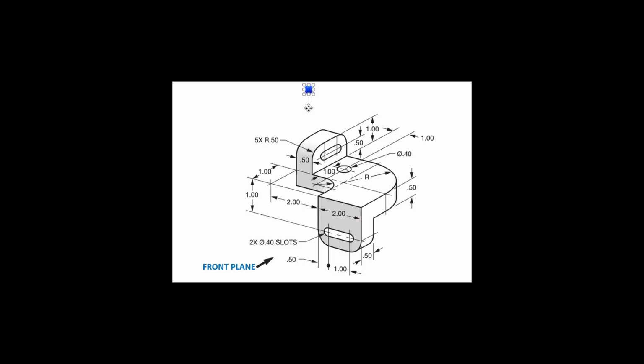the origin. It is arbitrary, but I can specify for whatever reason that I want, say, the origin to be at this location. It could be anywhere else, but for the purposes of this video, we will say that that's where the part origin is going to be. And that part origin is then going to allow us to take a look at the mass properties and locate the center of mass of the part with respect to a point of our choosing, as opposed to an essentially arbitrary location, depending on how we create our first sketch. But here someone else is specifying where the part origin is supposed to be.